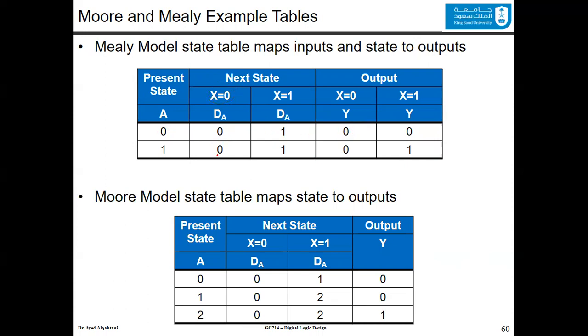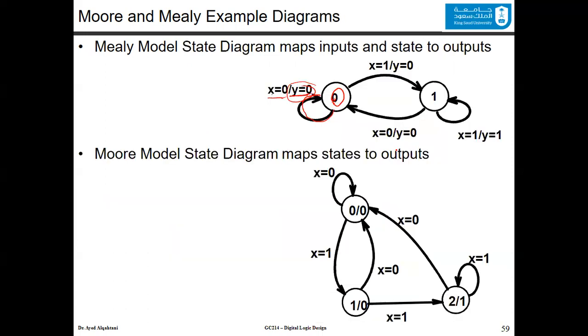When you write the table this way, you could write the 0 and 1, 0 and 1, 0 and 1 initially, and your job would be filling those 8 values. You fill these 8 values based on the 8 values here. There are 4 outputs and you have 4 transitions. The end of every transition is a next state. So the total is 8.